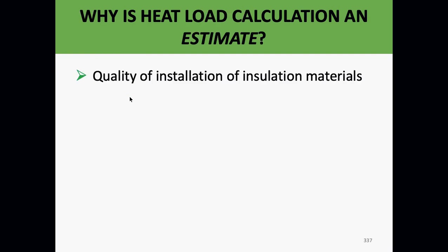Okay? What we don't know when we're looking at a house is we don't know the quality of the installation of insulation materials. There could be big gaps in the insulation. Okay? We don't know the overall construction quality. I don't know what's in the walls. Okay, I don't necessarily know what's in the basement cinder blocks. I don't know if they were insulated. I don't know if they were concrete filled unless I can see the top of them, and then I don't even know if it was done all the way through. I do not know the construction quality, especially in some older houses. I'm not even sure the people who constructed them are around anymore.